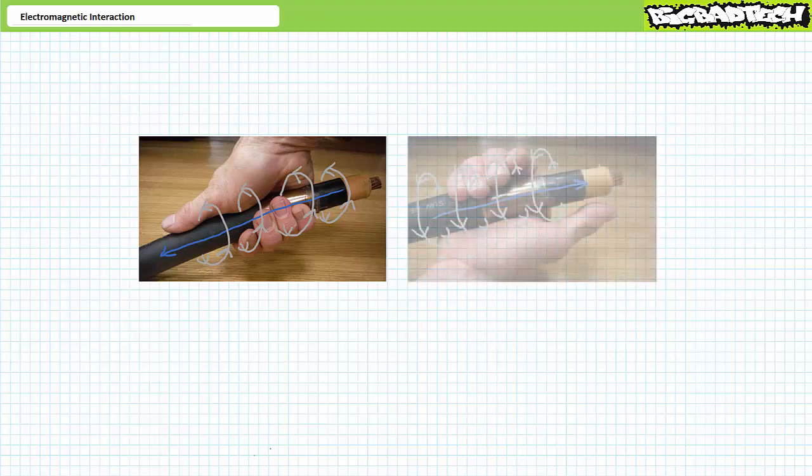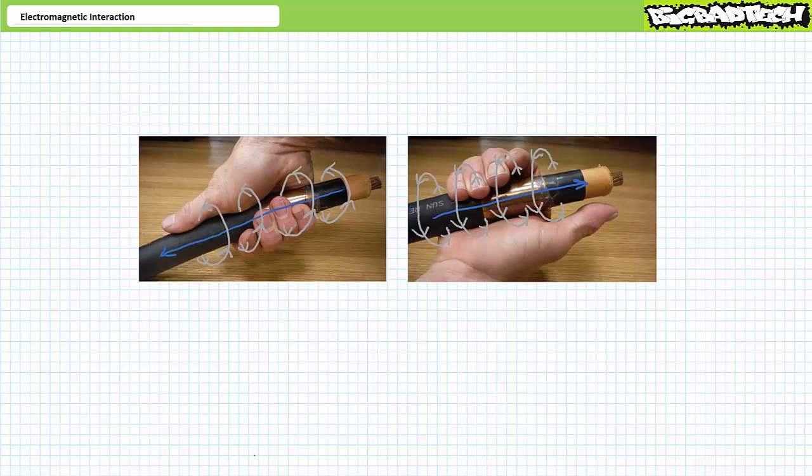It is an observable fact that as conventional current moves through space, it creates a magnetic field around it. The polarity of the resultant magnetic field can be predicted by holding the right hand in a loosely held hitchhiker pose with the outstretched thumb pointed in the direction of conventional current flow. The curling fingers indicate the polarity of the revolving magnetic field, north to south. You'll note that current flow in one direction creates a given magnetic polarity orientation, whereas current flow in the opposite direction creates a magnetic field of opposite orientation.